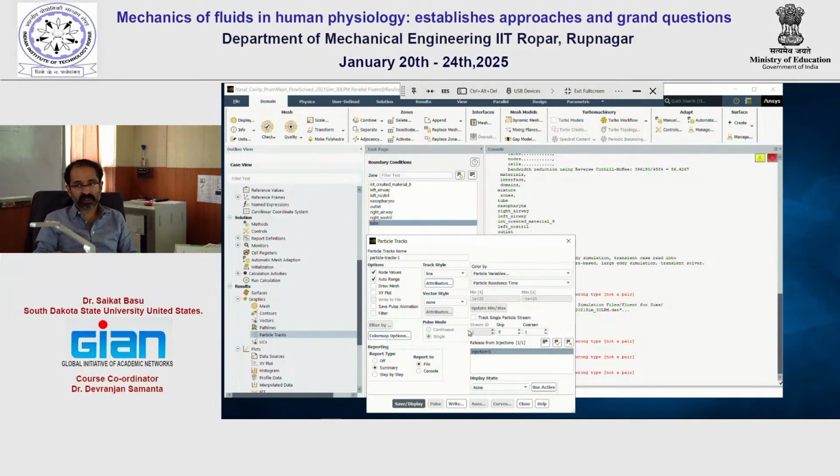We have set up the particle sizes, we have set up the cone, and we have set up the boundary conditions of the walls. We have not told ANSYS anything about the formulation of the material properties. So that we have missed, and we have to fix that. So let's close this again.